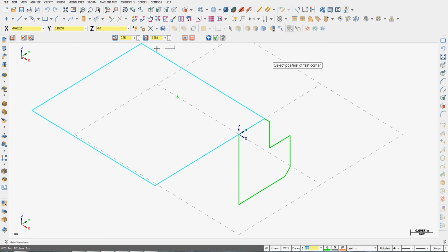So I've just entered a simple equation. I'll press enter. My rectangle will change. If I've made a mistake, not a problem, I'll do it again. So that was minus 0.375 plus 31 thou plus 31 thou, and I fix it up. If I'm happy with that, I can apply it, or if I'm done creating rectangles, I can say OK.